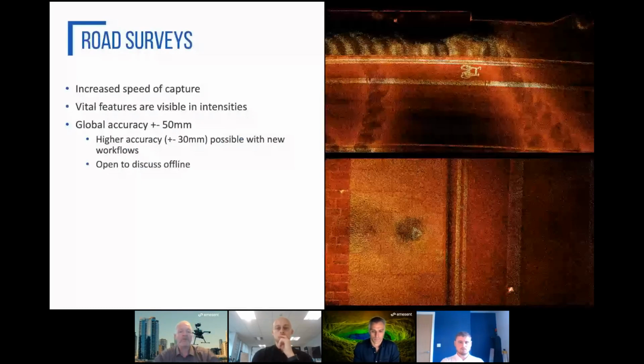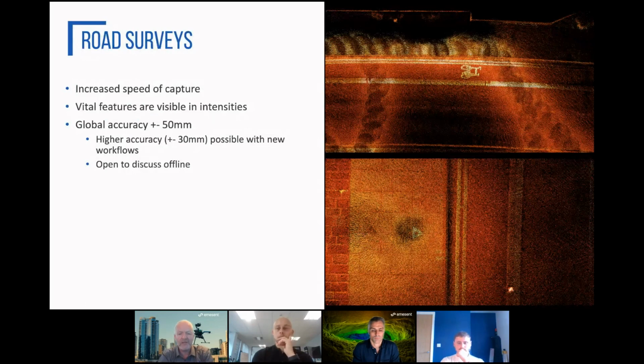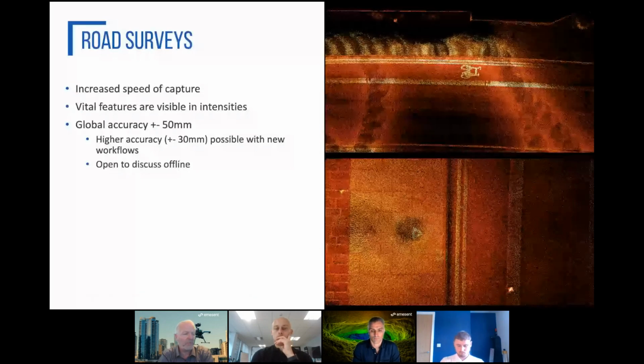But before that, I wanted to also cover one of the key areas, especially within surveying, which is the ability to pick up and do road scans. Now, the interesting thing with road scans is SLAM has recently been failing in this area, because you can't pick up what the surveyor needs. You can't pick up the road markings. Look at the bottom right-hand side here, you can see the small triangle. This is the spray marks from the surveyor, the control points. That data typically isn't able to be picked up, but because we developed a solution from mining, where we needed that data to provide the service we do, for road surveys we are picking up sufficient data.